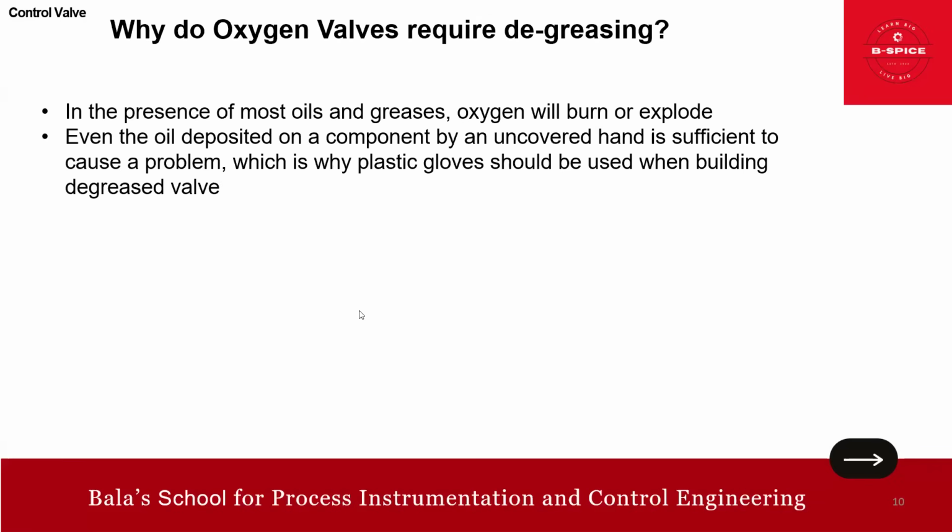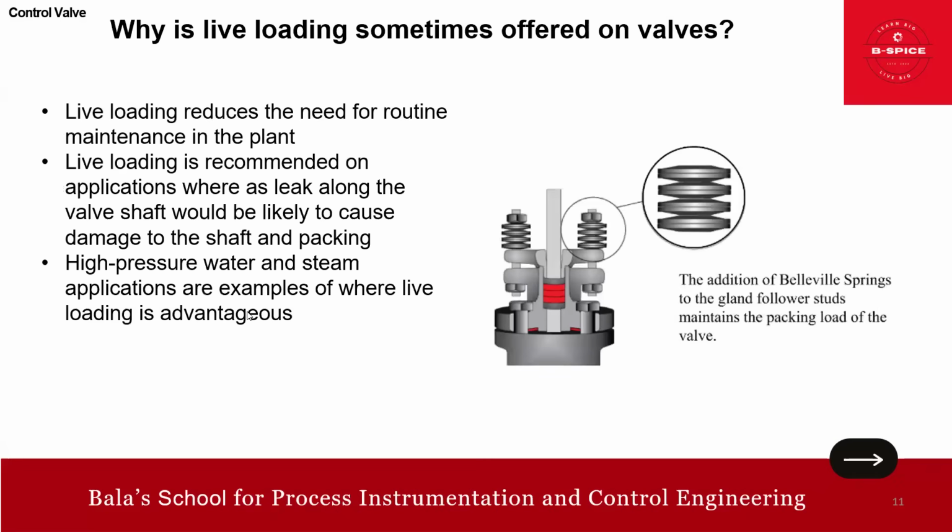Why do oxygen valves require degreasing? In the presence of most oils and greases, oxygen will burn or explode, right? So even oil deposited on a component by an uncovered hand is sufficient to cause a problem, which is why a plastic glove should always be used when building a degreased valve. You got it, friends? Yes, that's the point.